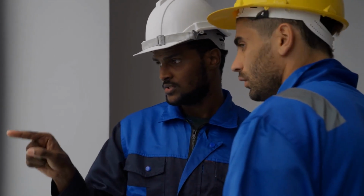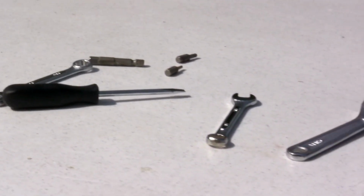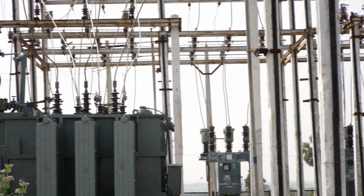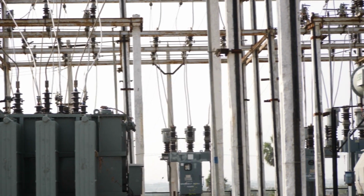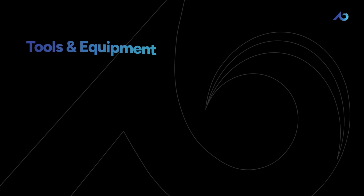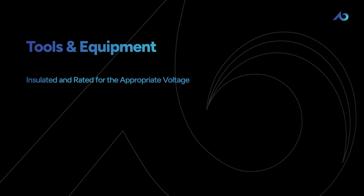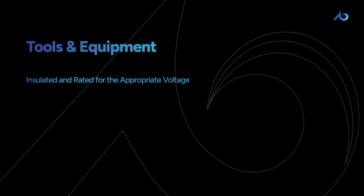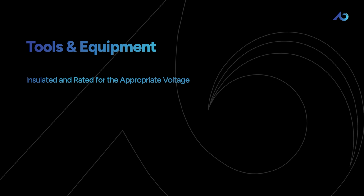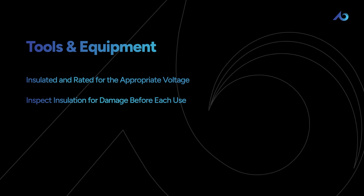Also, a discussion on equipment wouldn't be complete without mentioning the tools themselves. Remember how an accidentally dropped wrench could short-circuit a high-voltage system and cause the one thing we've been trying to avoid? It's not just about protecting your body, but preventing an arc flash in the first place. So even if you're already insulated head to toe, your tools need to be too. That means everything from your screwdriver to your portable ladder. Anything that could come into contact with live equipment should be rated for the voltage you're working with. You should also inspect them for damage before every job to make sure their insulation is intact.